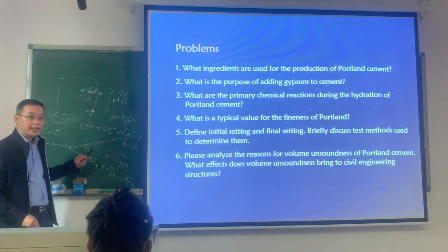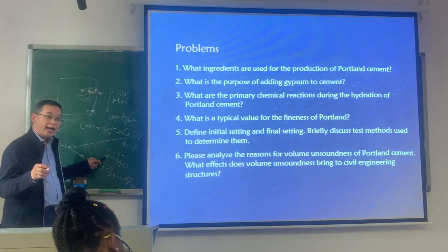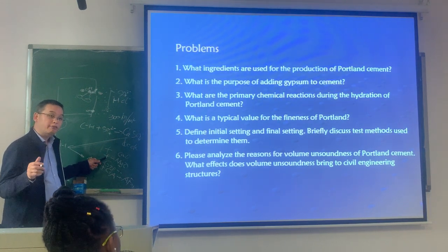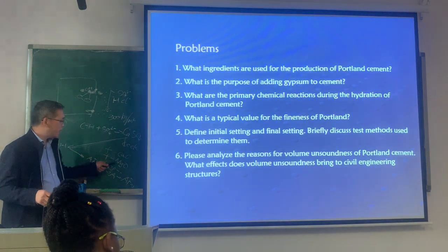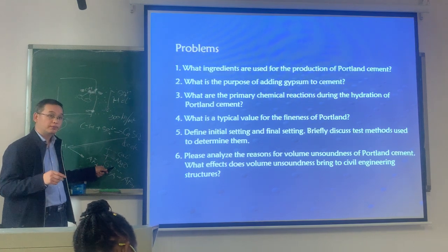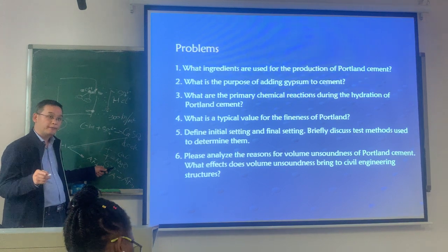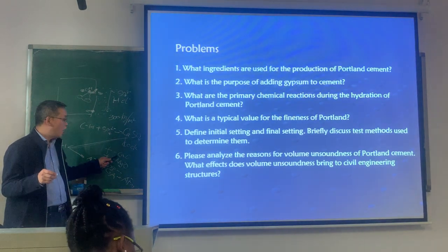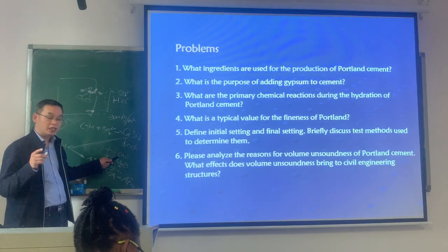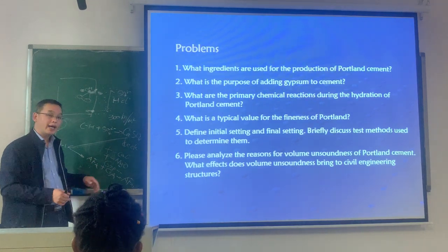The reason why these three substances result in bad volume soundness is that, firstly, their reaction is very slow. It will react after the hardening of the cement paste, and then the reaction product is expansive. So this is the reason why it expands.